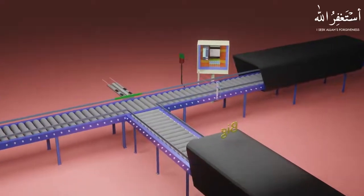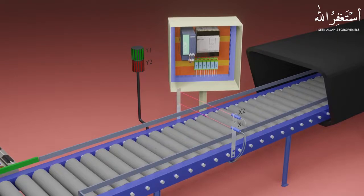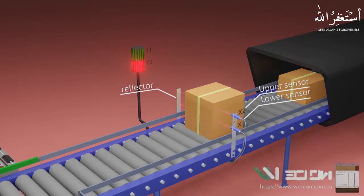Let's discuss the setup for today's tutorial. We have a roller conveyor. Boxes will be traveling on this roller conveyor. These boxes are of two different heights. To detect the difference in the height of the boxes, we have installed two beam photosensors on one side of the conveyor, and on the opposite side of the conveyor we have installed the reflector, to detect the beam of these sensors. When an object comes in between the sensor and the reflector, it will cut the beam of the sensor, and the sensor gives an output signal at the PLC inputs X1 and X2. These sensors are connected at X1 and X2 PLC inputs.